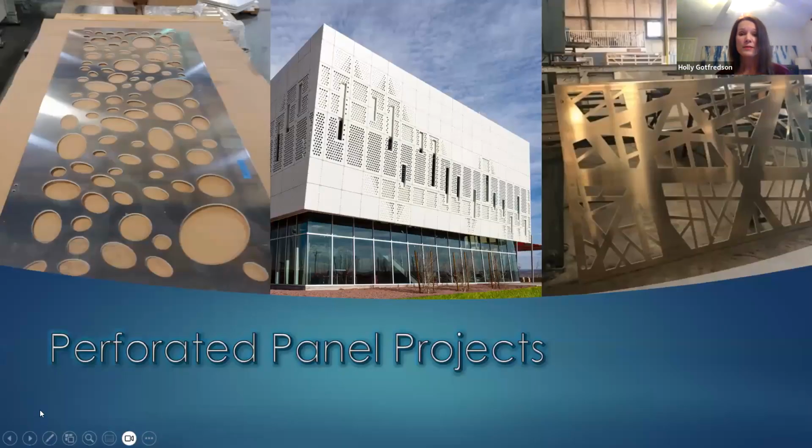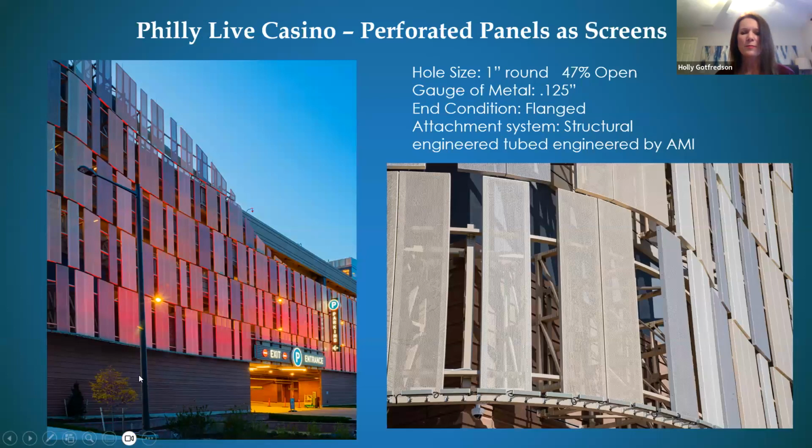So, different types of examples of perforated options and projects. There's a couple of different ways to attach. We're going to talk about structural versus face fastening today. You'll see examples of that. This particular project, we utilized 1-inch round holes. It was about 47% open.